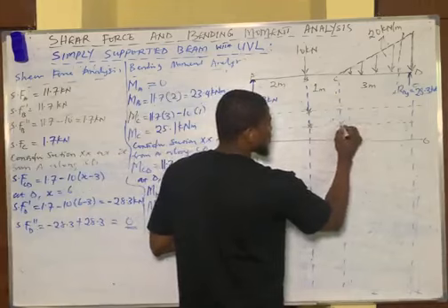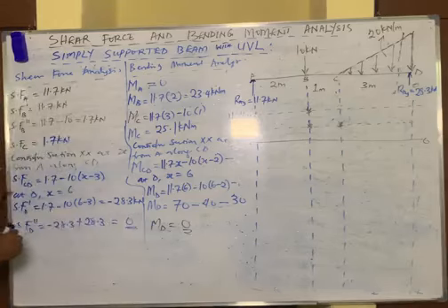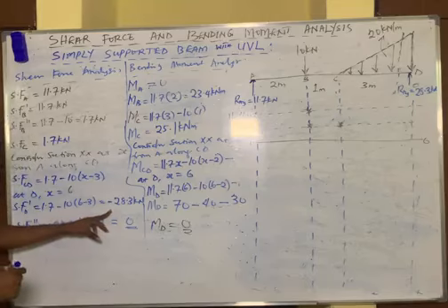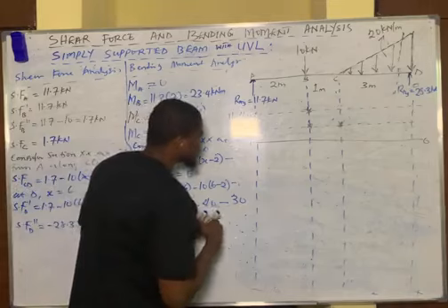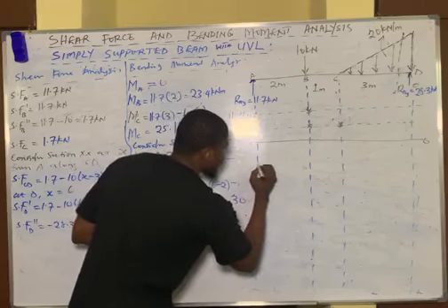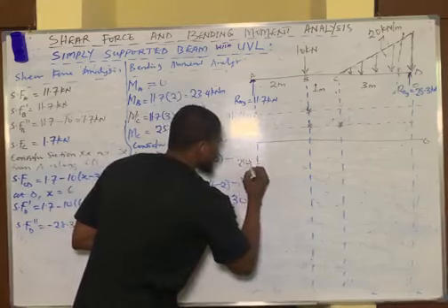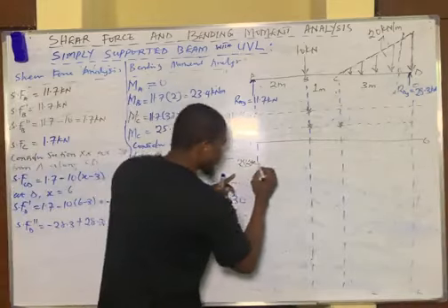On getting to point C, it encounters a strange load, which took the shear force to point D initially to be negative 28.3. Okay, so we have negative 28.3. So let's indicate that here. Negative 28.3 should be somewhere here. Negative should be down, right? Below the 0 mark. So trace it out.